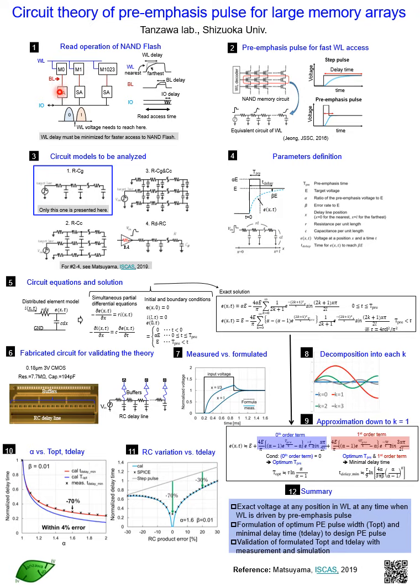The sensor amplifier senses the bit line voltage lower or higher than the reference voltage. Then the sensor amplifier can detect the data of each memory cell and latch the data 0 or 1.